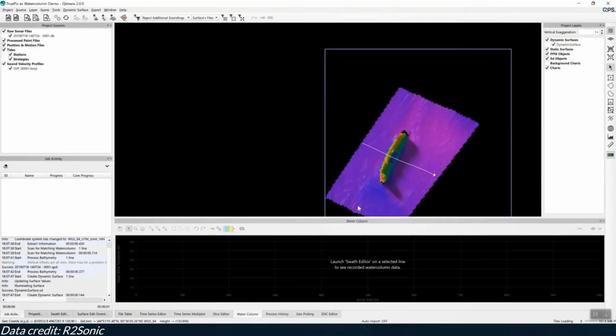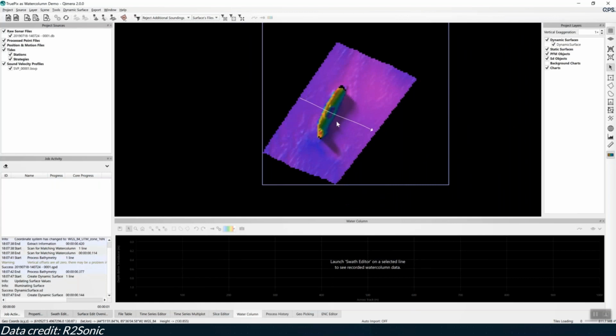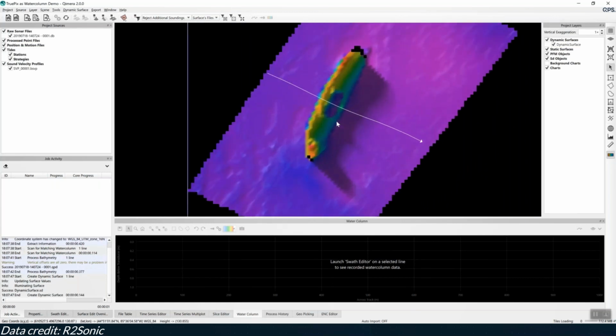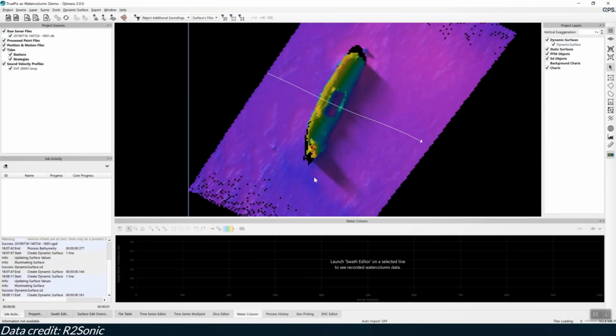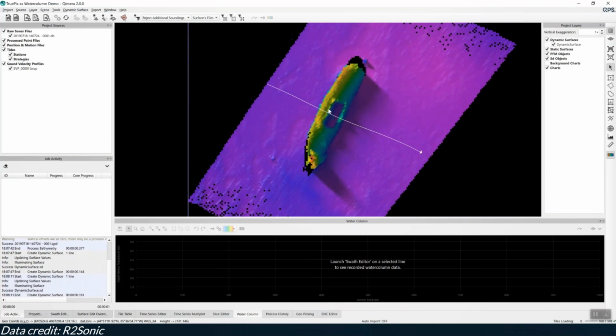We'll leave it at the defaults, 50 centimeters. And here, I'll just take a side tangent. You can look at that dynamic surface and it's a little coarse. There's a new feature that you can right click on a surface and change the resolution quite quickly. So if I see that it's a little too coarse, I can choose to change the resolution. Let's go to a quarter of a meter and then click OK, and that regrids and I get better resolution there.